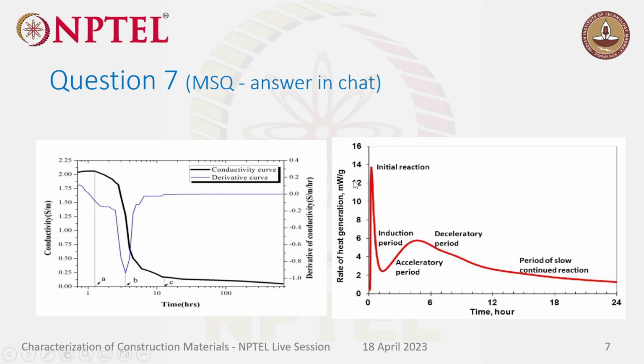Once you mix water with cement, there will be a sudden release of heat, because two phases, solid and liquid, are mixed and cement has a lot of ions in it. There is a sudden burst of heat because cement has some amount of alkalis and alkalis are readily reactive, so they readily get into the solution. Alumina kind of phases will also have more heat generation. So the sudden heat of wetting can be due to that.